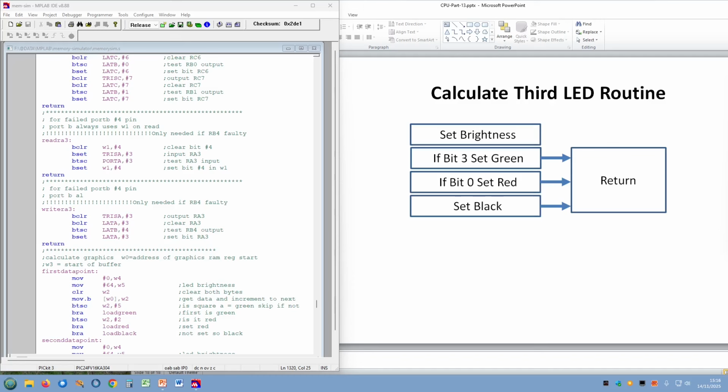So I've come to the conclusion I've either got fake chips, or these ones were rejects that somebody's got hold of and sold on. I mean, if I'd known those I/O were dead, I would have built the board slightly differently. So only buy from a reputable dealer. Don't get caught like I did.